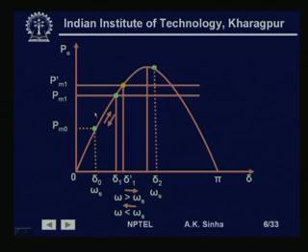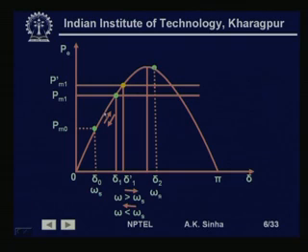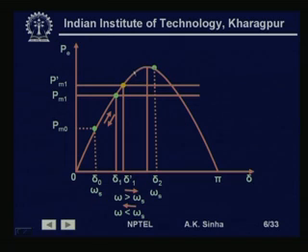So, what is going to happen at this point? Once the speed reaches synchronous speed, since acceleration is still taking place, the speed is going to increase to more than the synchronous speed. So, again delta will increase, and we will find delta will keep on increasing. Once it reaches this point, we will find that the speed of the rotor has increased beyond the synchronous speed. Though Pm and Pe will be equal, still, the speed being more than synchronous speed, delta will keep on increasing and it will again come to this point.